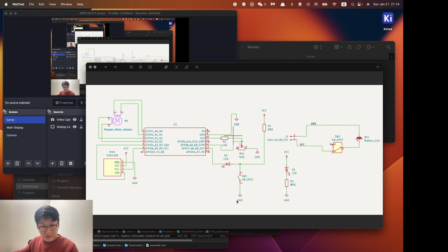What I want is a potentiometer to adjust the analog input reading, and then I can use it to switch the angle of the stepper motor. Another thing is the button, which is used for setting that analog reading as the next stepper motor's target angle. So I need to finish those two parts next.